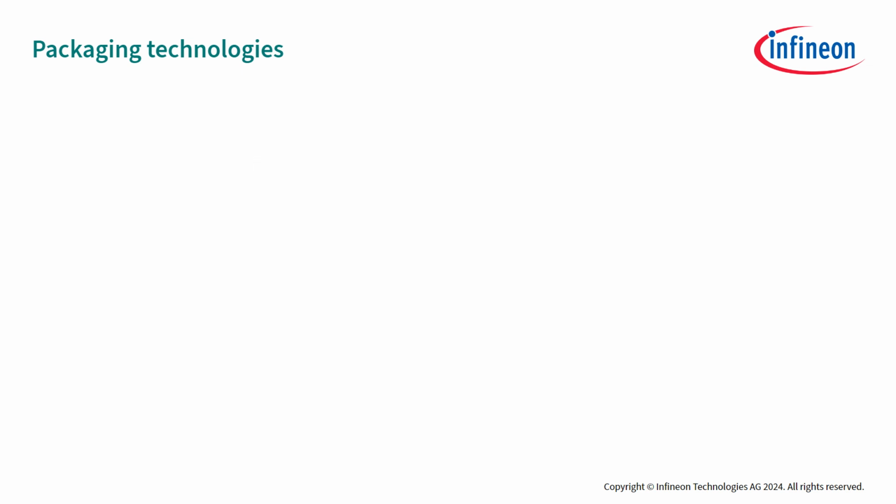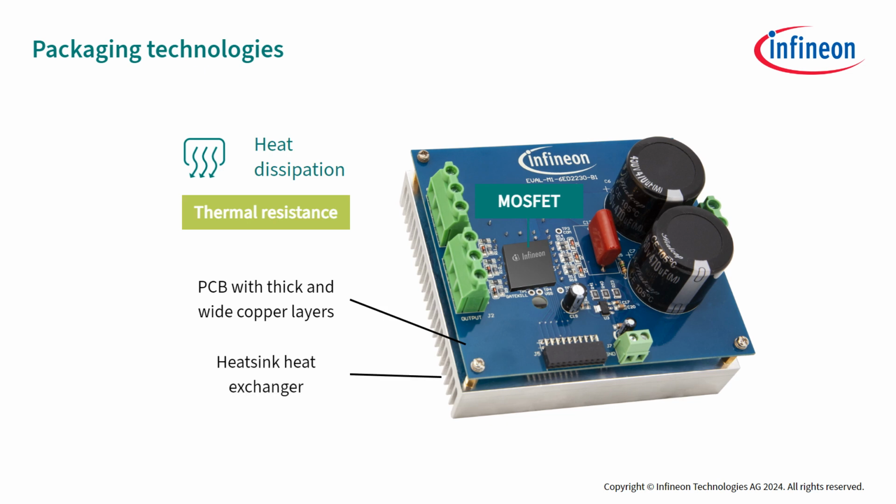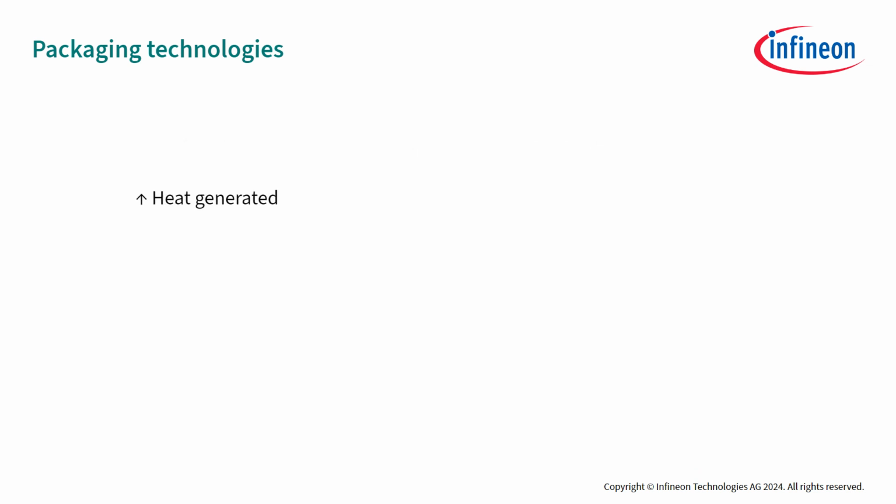So you can achieve effective heat extraction or heat dissipation by physically attaching the MOSFET to a material with a big mass that is a good heat conductor. If this is not the case, the MOSFET will heat more, which may lead to reduced efficiency, maximum current capability, and reliability, as previously mentioned. For this reason, the more heat that is generated, the more efficient the heat sinking mechanism needs to be, or, in other words, the lower its thermal resistance needs to be.